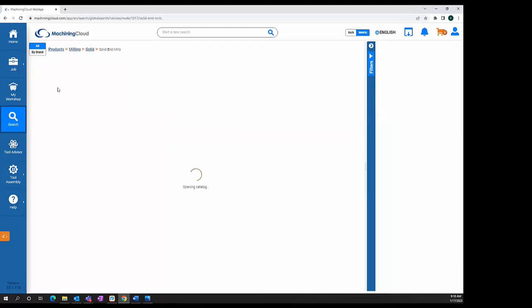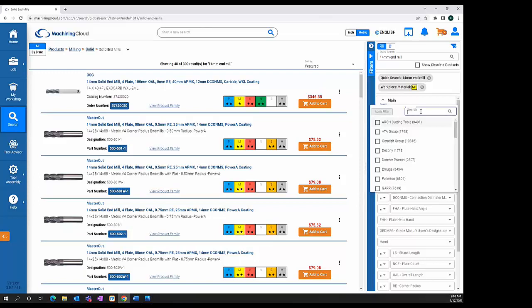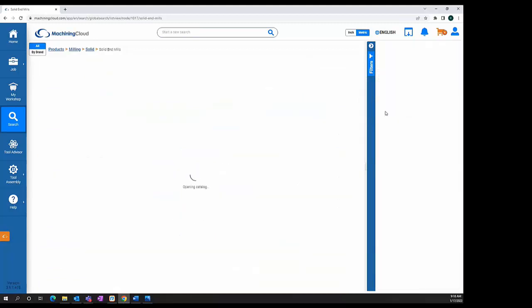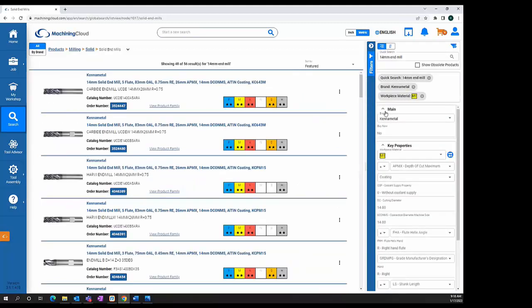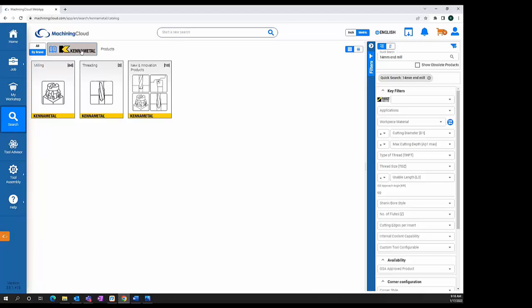Again, we're going to go with solid. And what we'll do first is we'll go by brand. So if I come up here I can select, say, Kennametal. Also, you can change that up here as well. So as you can see, we're already in Kennametal.